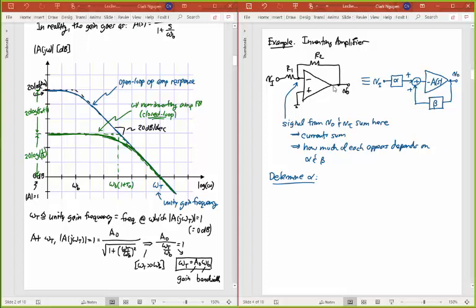You can think that makes some sense because in an ideal op amp, usually you have a very small resistor at the output, and that's going to ground if you have no voltage going through this thing. Okay, that's just sort of a hand-waving argument I'll give you right now. 140 will teach you much more about why this is. And if 140 doesn't, then 240B will. Sometimes 140 doesn't get to it, actually. But right now, the procedure is 1, ground the output.